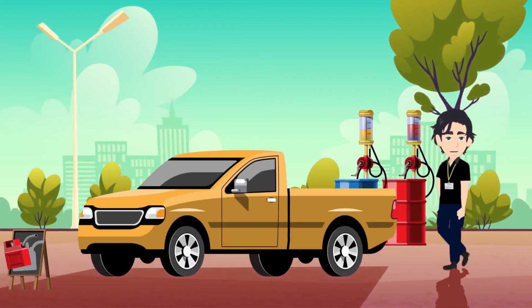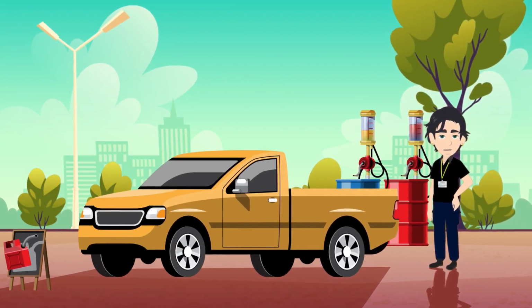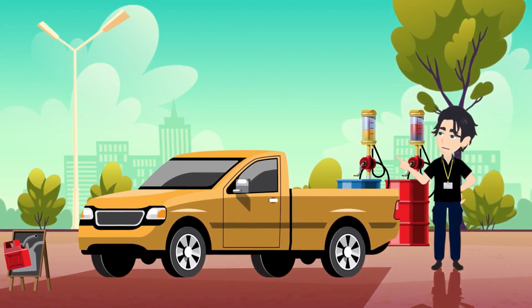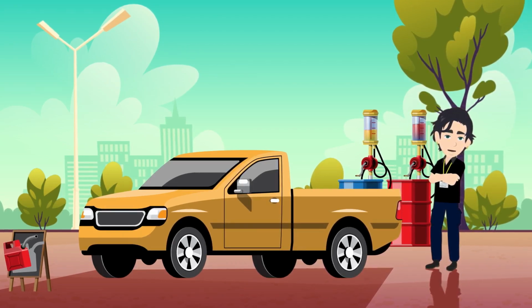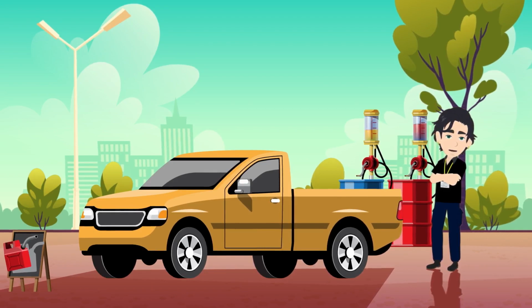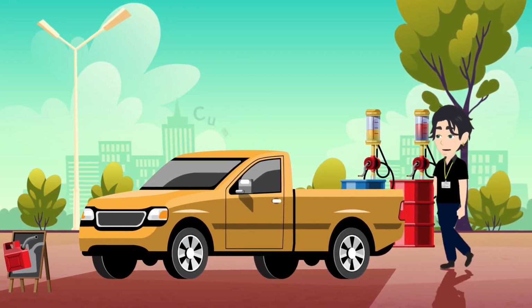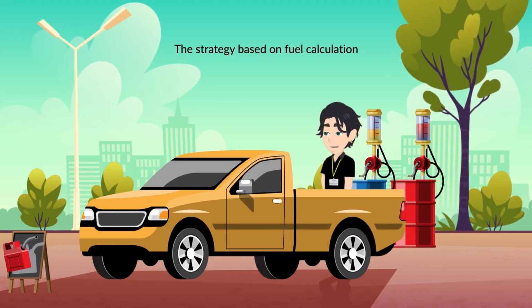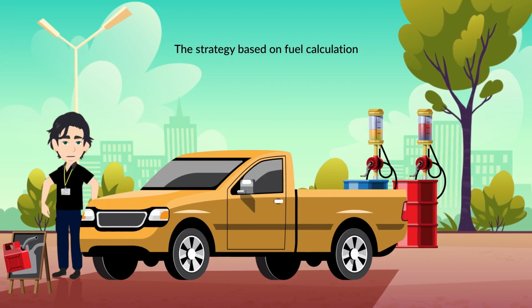For this reason, the MFM strategy was only used for a few years, until the early 2000s. So the few vehicles that you might find yourself modifying using this strategy are very dated, medium and large displacement engines, such as the Cummins. Subsequently, the strategy based on fuel calculation has increasingly taken hold, then arriving at the strategy featured in the following videos, torque calculation.